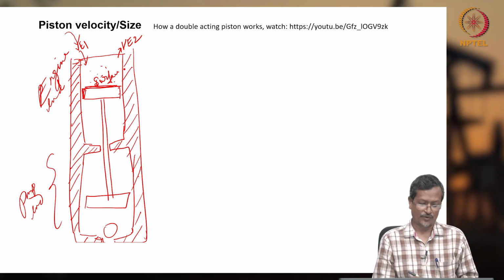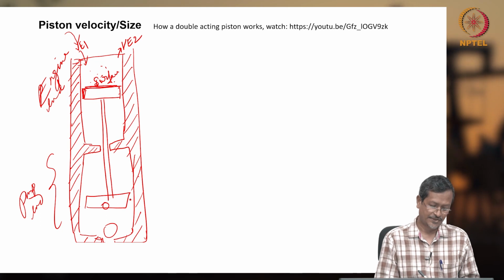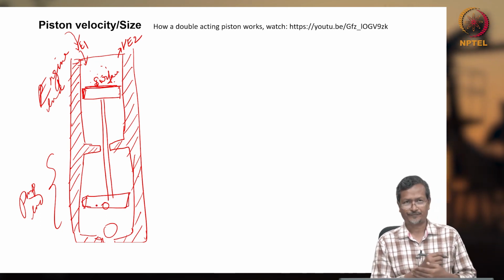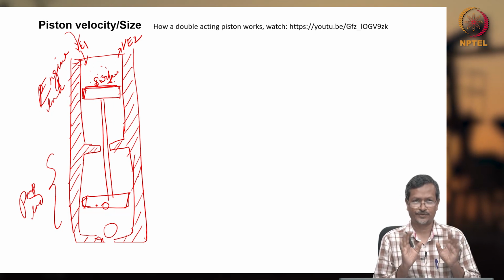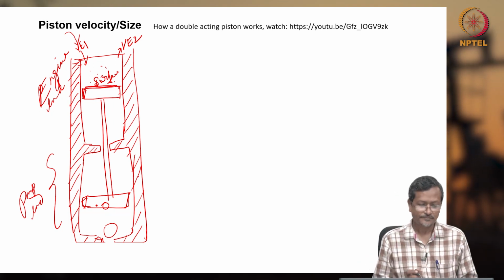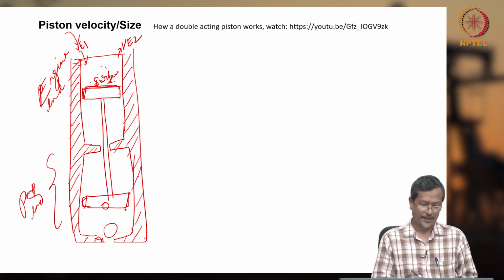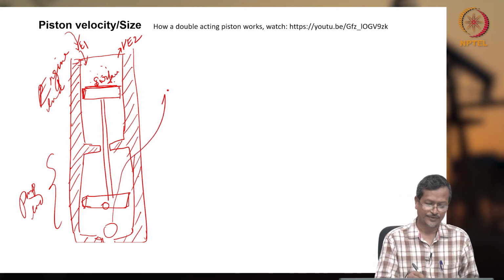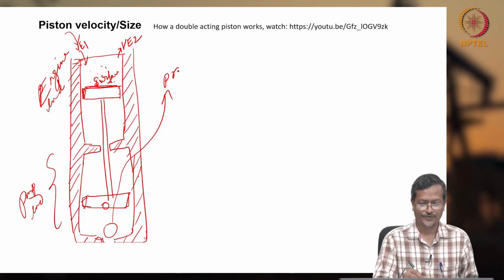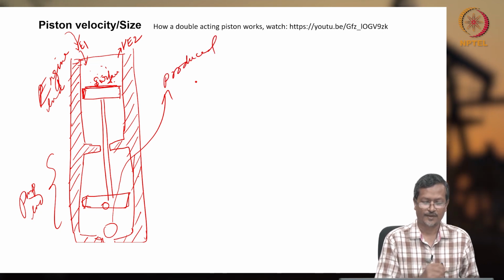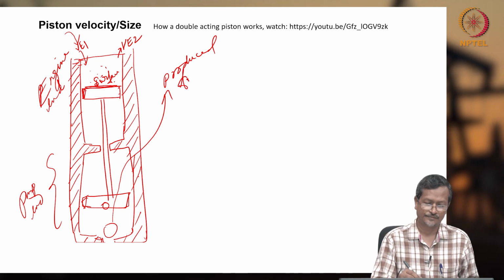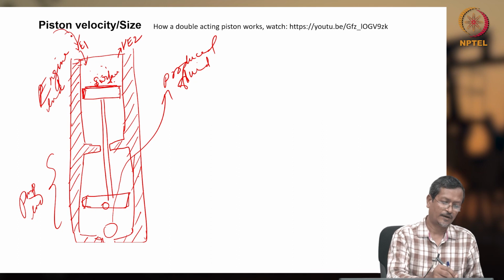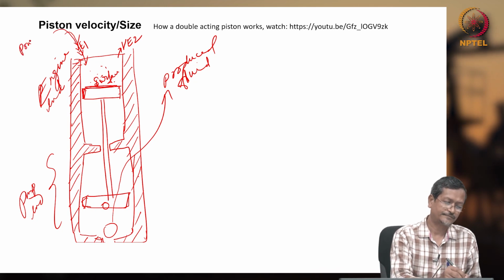When pushing down the rod, this piston will have the sucker rod pumping mechanism, right? Similarly, we assume a sucker rod pump. This plunger assembly is there at the bottom. The piston is moving down and fluid is entering and going through this. Okay, produced fluid or wellbore fluid, and this fluid is power fluid.